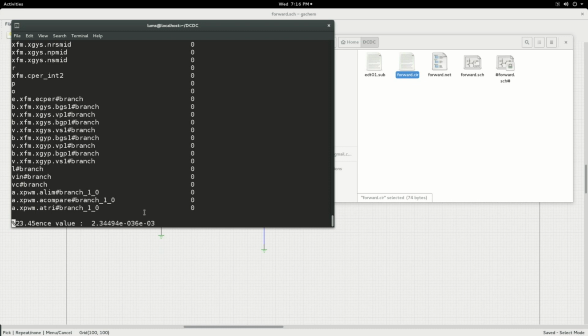The first time, the simulation will take quite some time, basically because you would have given an extended range till it reaches steady state. After it reaches steady state, you can note down the steady state values and give them as initial conditions, and do the simulation with those initial conditions. Then you will see that in just a few cycles you will quickly get the waveforms that you actually would like to see at various parts of the circuit.